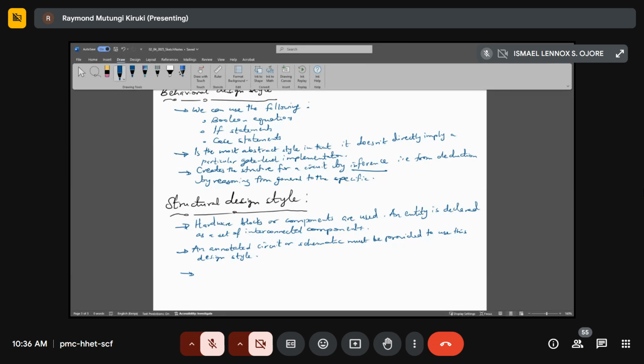So we'll talk of instantiation, and this, as I've described, is analogous to calling functions that have been declared elsewhere. In this case, of course, we're dealing with circuits and some components we have defined and described in a different VHDL file, but we now want to put everything together. So in our main VHDL file, we instantiate the various modules or components that we have declared elsewhere.